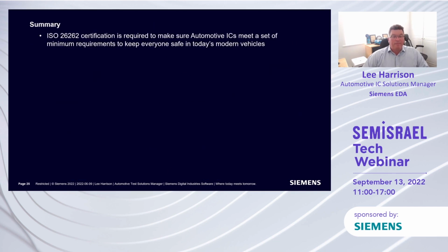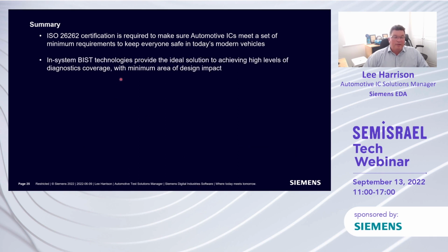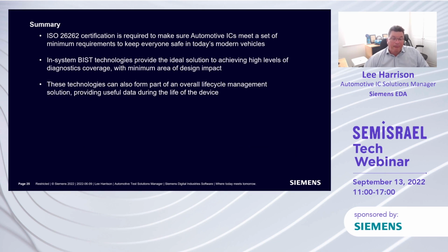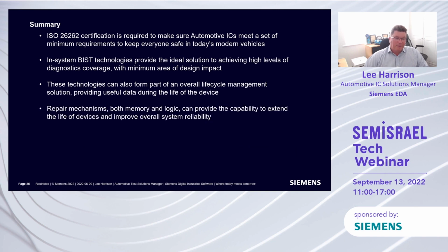So in summary, ISO 26262 certification is required for all automotive ICs. The in-system BIST technologies provide the ideal solution to achieve this very high diagnostic coverage, which is required. The technology can also form part of an overall lifecycle management process, so really looking at the life cycle of the device.